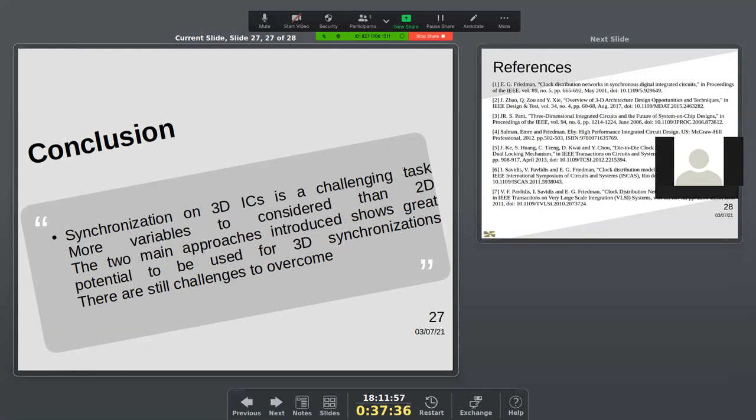And also for the clock distribution network approach, we didn't have the flexibility to have a non-symmetrical design between die 1 and die 3, whereas in some design constraints that could not happen, so we will be needing more research into figuring out how to depend on clock distribution topologies to do synchronization without having them be exactly symmetrical.